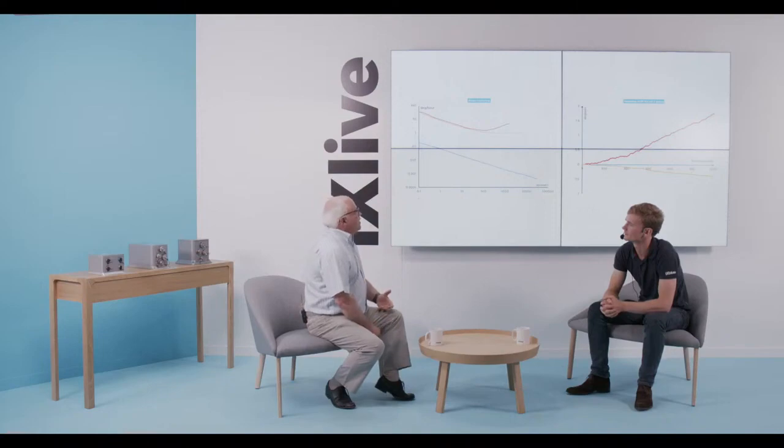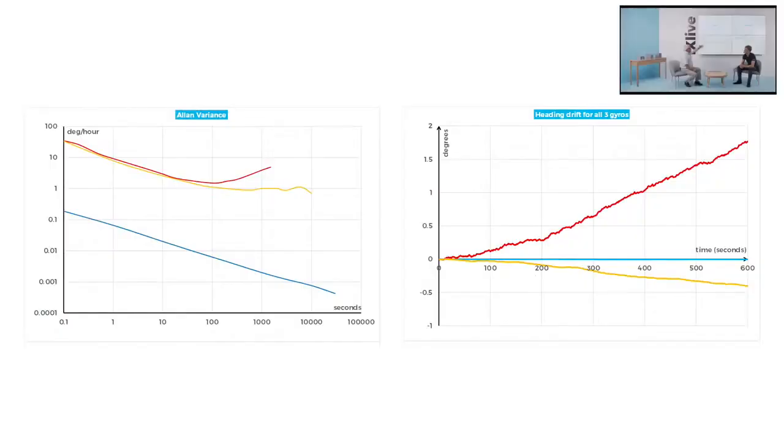In actual life, in an actual mission, it would not be as good as it is here, for two reasons. The first one is that the Kalman filter before the loss of the GNSS would not estimate the biases as well, because the Kalman filter estimates a lot of parameters at the same time. And the second reason is that there are other factors which would affect the performance of the sensor and the stability of the bias of the sensor, which would be the temperature variation, the magnetic field direction, and so on.